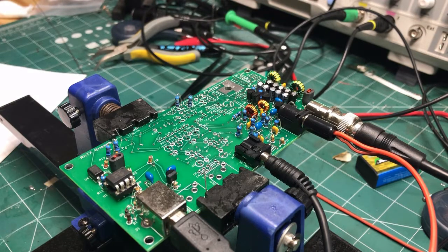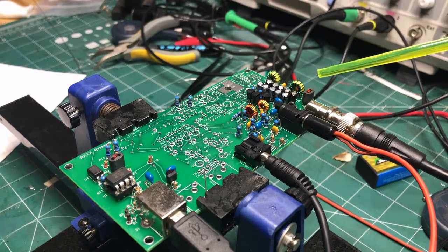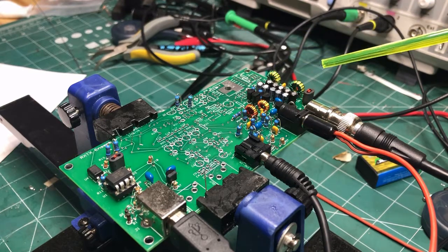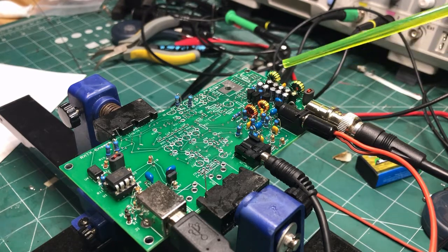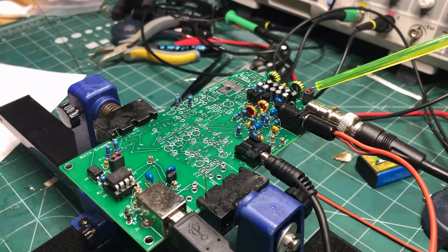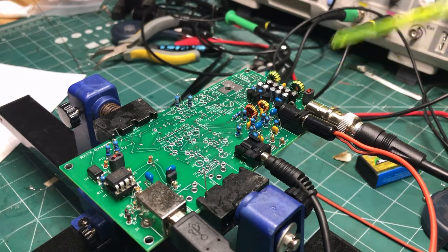Okay, so this is kind of the receiver final test and on the air video. The last video I mentioned I needed to install the low pass filter and the BNC connector. So I've installed those now. That consists of two 37.6s, each with 14 windings. And then the antenna is isolated from the LPF via this binocular core here, and that consists of 2 turns bifilar.